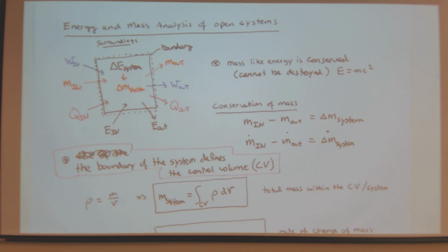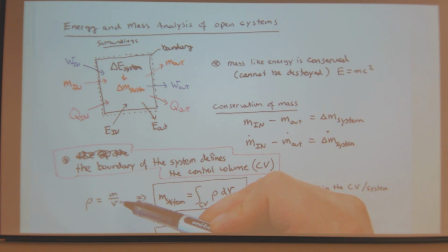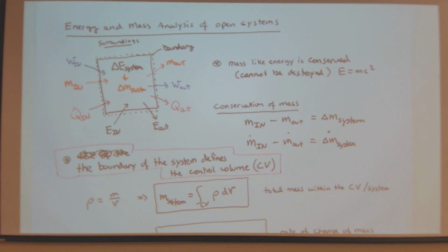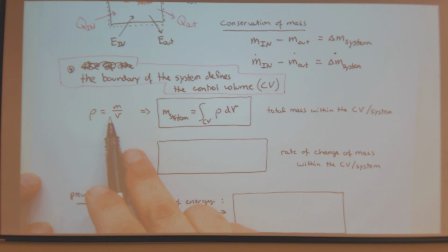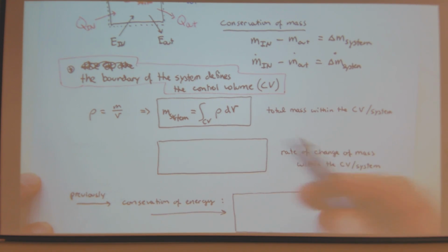So it's just the integral form of the total mass of my system based off its density. And I could say constant density within my control volume. It's a constant, moves outside the integral, and basically all I have is my volume, and it comes right back to that, right? But density within my control volume could have a distribution, and then I would have to take that into account. Okay. But mass of system related to that, just an integral form of this expression, right?